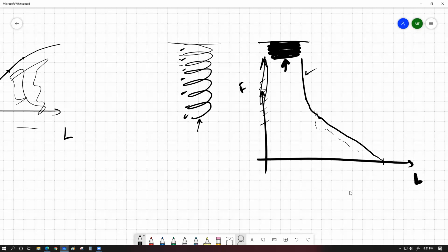I definitely agree to this point, because as far as my experience goes, any spring that is manufactured is designed to behave like an elastic material till the last point of its compression. Whenever the coils touch each other, within this point, it behaves as an elastic spring. If that's the case, then we might actually have a really sharp point over here. There might be a very beautiful straight line, and then it goes sharply upwards like that.